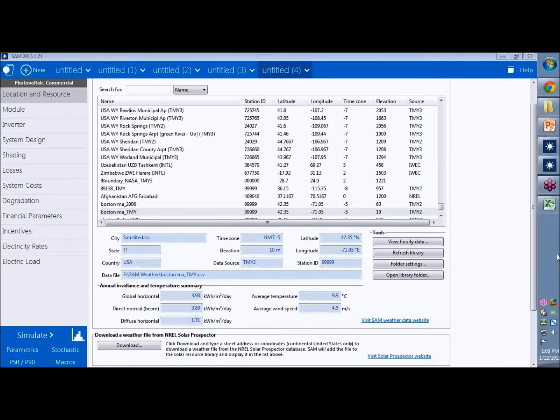There's also other software that does that a little bit better, that's more designed for off-grid and microgrid situations. Like HOMER is an example that I can think of. So at the moment you can't model that at all in SAM because there's no storage model. After the summer, there may be some ways to start getting at that question, but SAM isn't designed to specifically answer those sorts of questions.